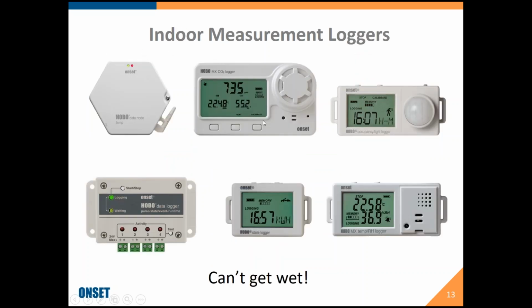Here's a typical sampling of some of our Onset indoor loggers. And the key thing to remember from this slide is indoor loggers can't get wet. They can't have dew form on them, can't have frost form on them. They can't be put in an environment where they could get wet, such as a greenhouse or a place that has condensing water. That's indoor loggers.